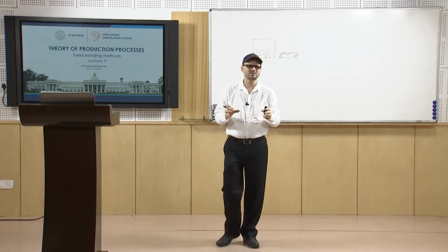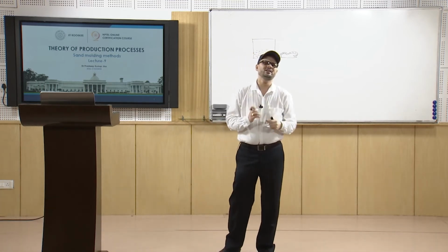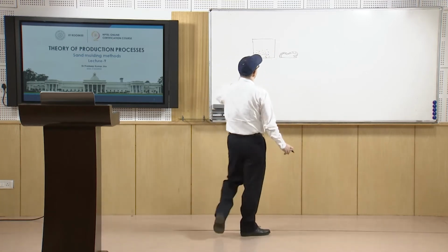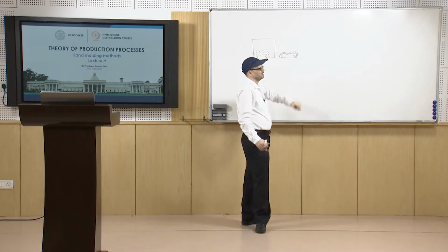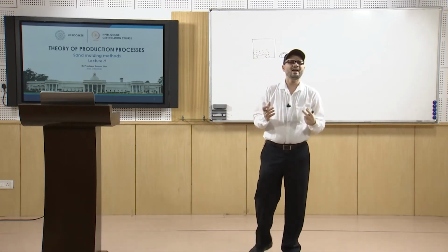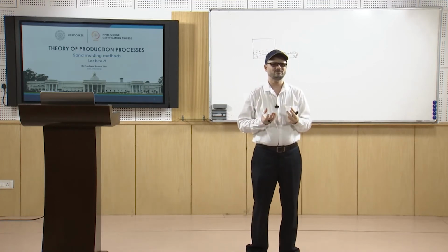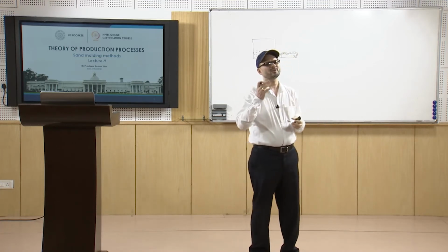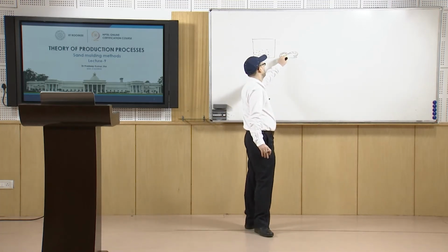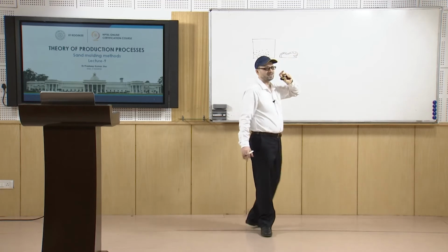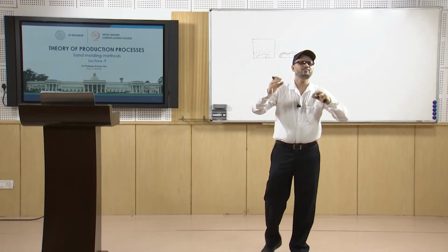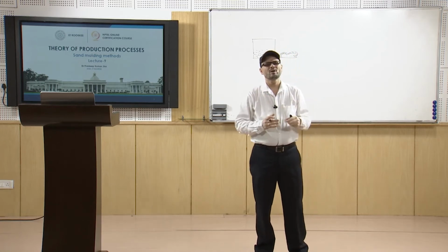Normally thermoset polymers are used, and because of the heat they get strength, so your mold does not need to be very thick, they are very strong, and they also provide very good surface finish. Normally they are used for making cores, because they are very thermally stable.